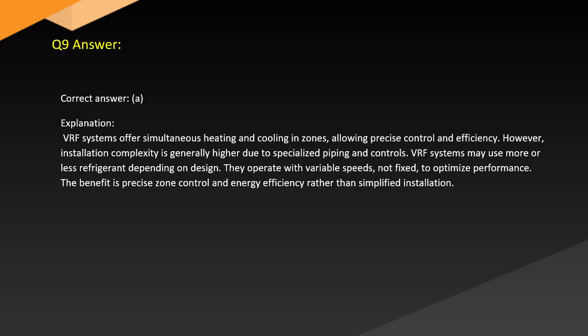Answer. Correct answer: A. Explanation: VRF systems offer simultaneous heating and cooling in zones, allowing precise control and efficiency. However, installation complexity is generally higher due to specialized piping and controls.